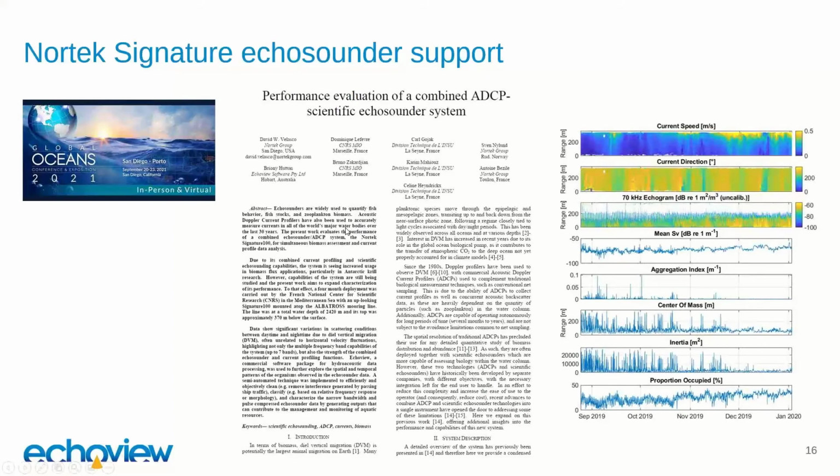For Nortek data, we have been collaborating with Nortek and some other co-authors to do a performance evaluation of a combined ADCP echosounder system. This is the Nortek Signature Profiler. This paper will be published as part of the Oceans Conference, which is in September this year. So this is a bit of a preview for a paper that is coming and a presentation at that conference. And basically we took the ADCP data and the echosounder data and just had a look at what we could see in this data for a 4-month deployment.